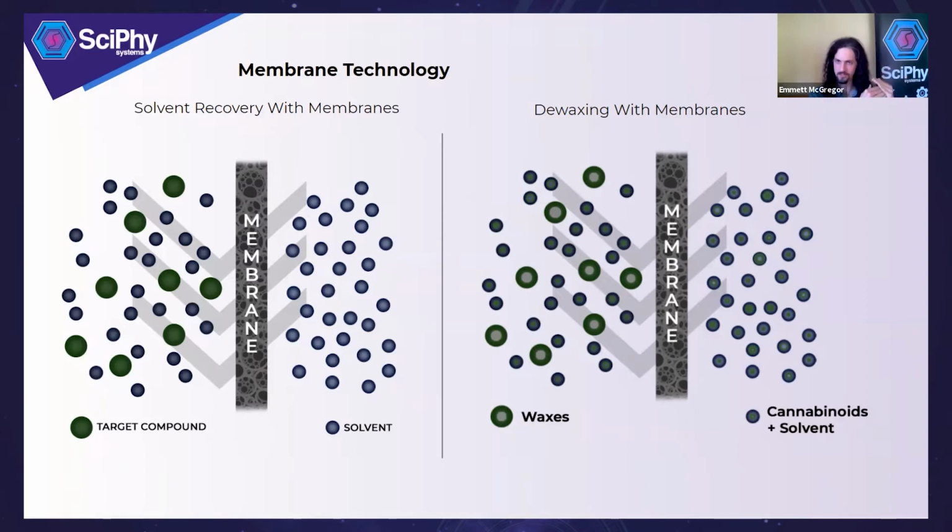So by integrating this on a flow-through basis with your extractor and with your downstream solvent recovery process, one operator can feasibly operate multiple stages in that process, and you're intensifying the process where your holding volumes are lower because you're able to constantly feed through the system. And so that means that your total volume of solvent, one of those materials cost contributors, can actually come down, and the regulatory burden relating to that holding volume of solvent can also come down.